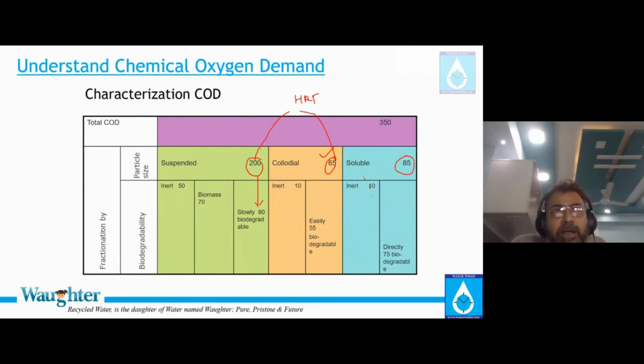important. HRT is important from the perspective of colloidal COD, but about particulate COD, which I'm talking about here, suspended, which is slowly biodegradable, even HRT is not important. The right important term is SRT. Why? Because here what is happening is, let me draw this material.